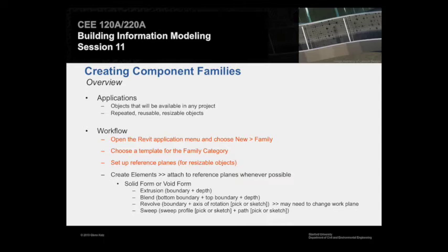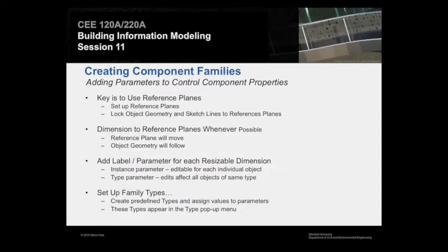Because what we're going to start doing is really defining the boundaries of objects through reference planes, and then lock the sides of geometry to those reference planes. Okay, so it all gets to creating reference planes that'll really be the bounds, and then stretching and moving those around.